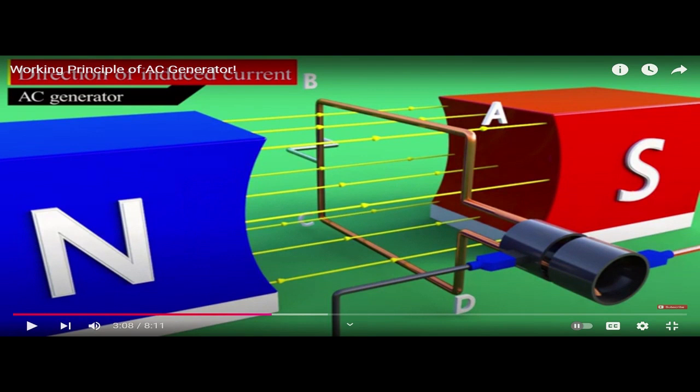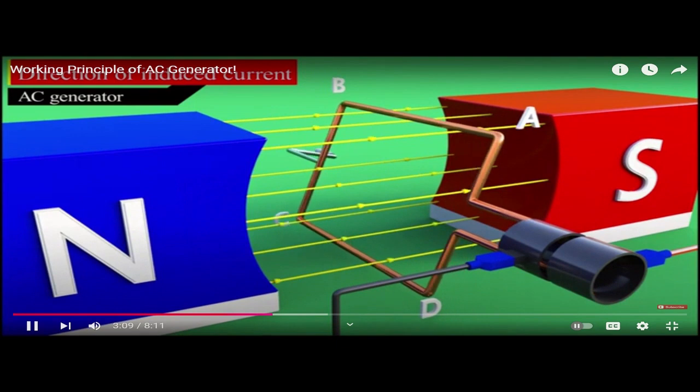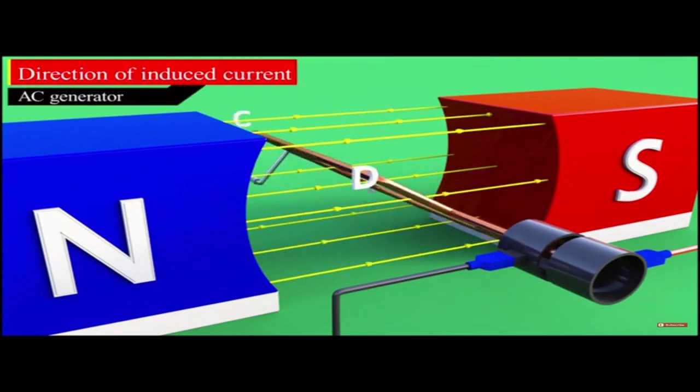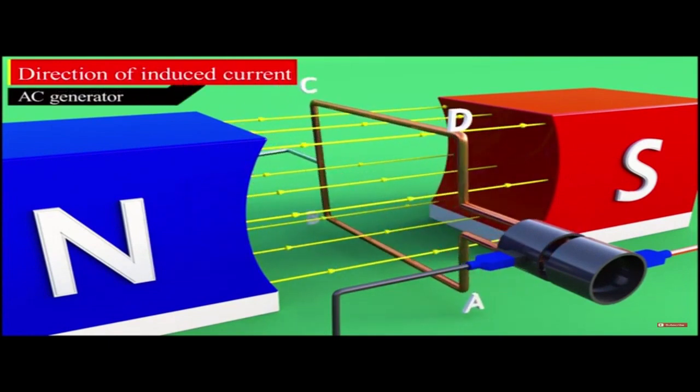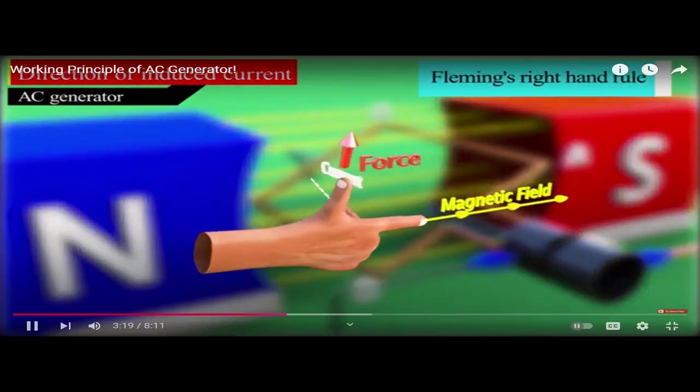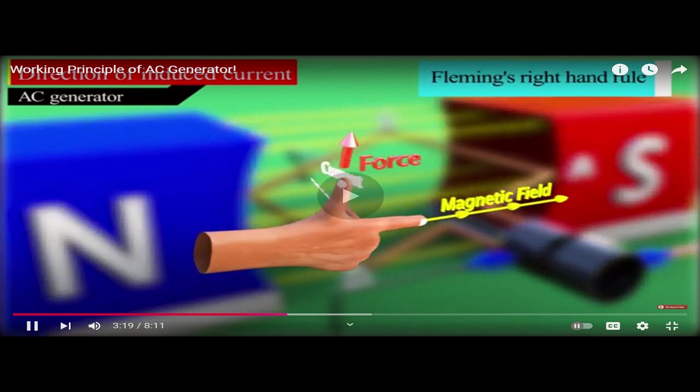Undergo half rotation in clockwise direction, part of armature AB goes down while part CD goes up. According to Fleming's right-hand rule, the thumb indicates. Okay, this one you don't have to worry, the Fleming's right-hand rule thing. Current will flow in direction DCBA of armature, and from brush B1 to brush B2 through galvanometer.